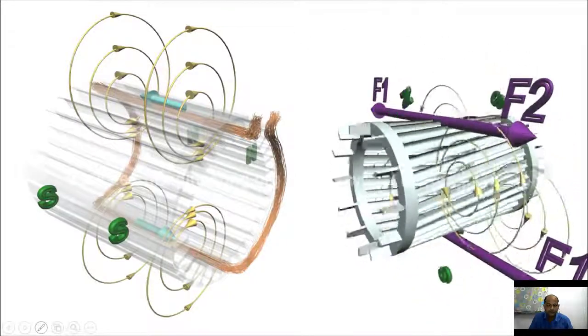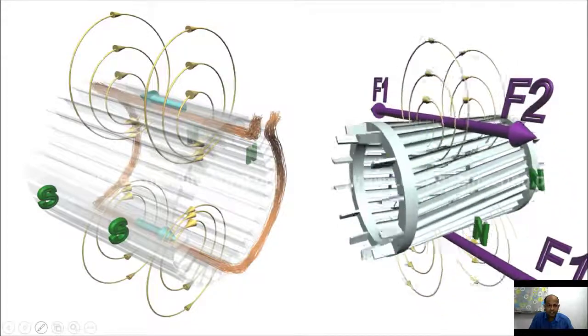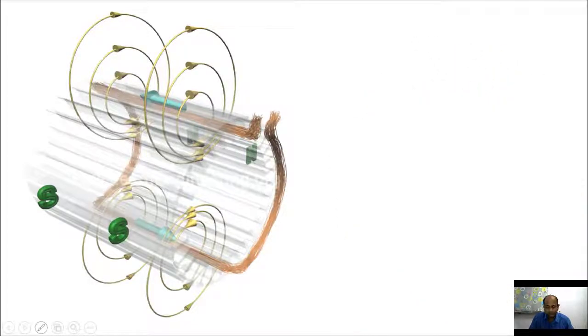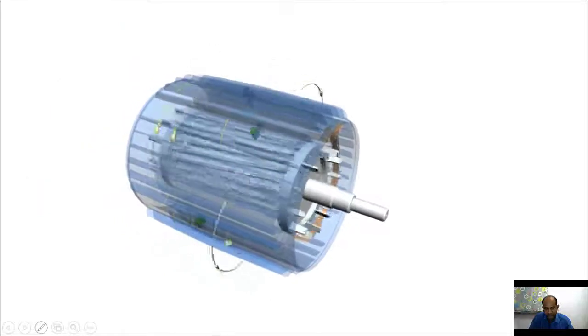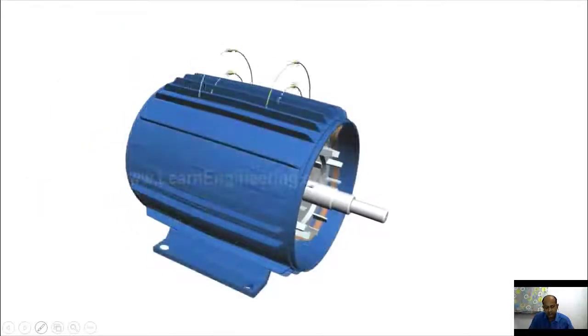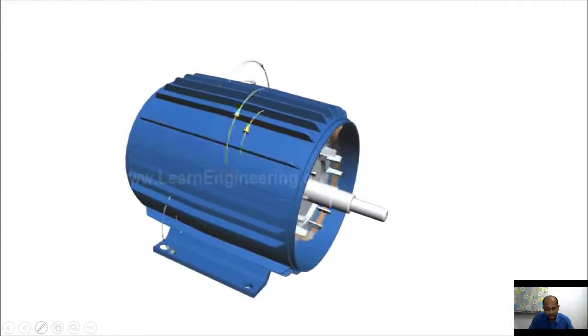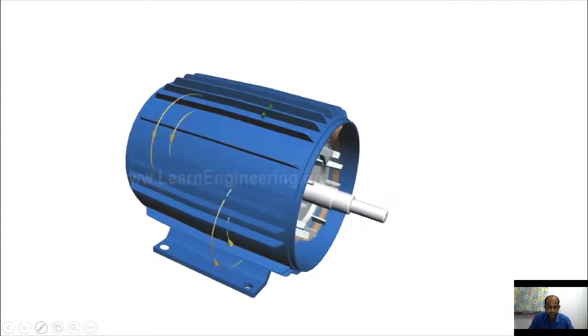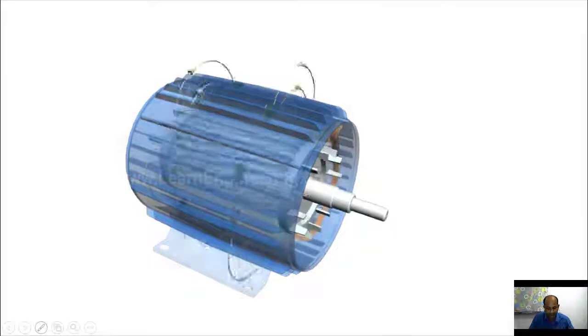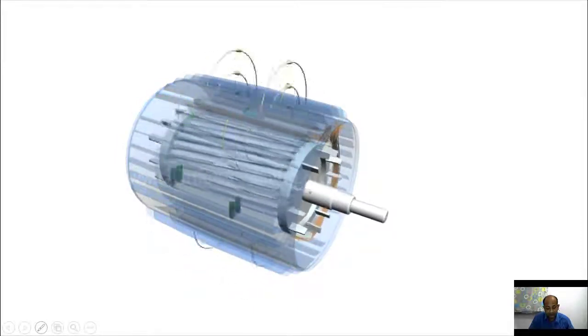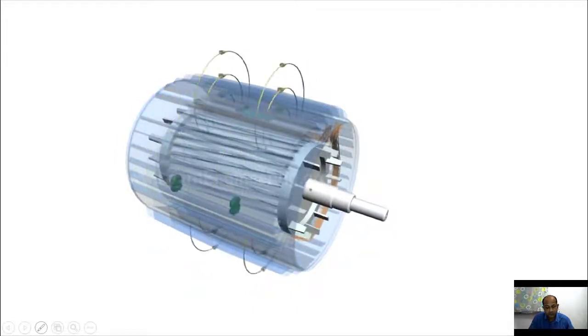Now Nikola Tesla has given this ingenious solution that if we can cancel either of the rotating fields, we will be able to start the motor. This can be done using the auxiliary winding and that capacitor. Now this auxiliary winding produces, similar to the main winding, two opposite revolving magnetic fields.